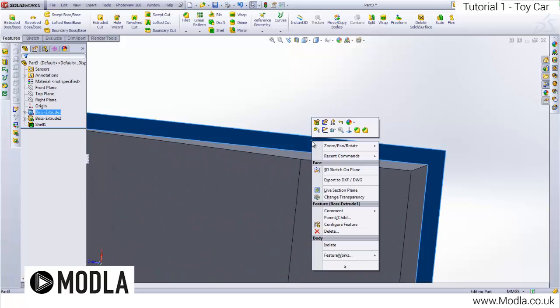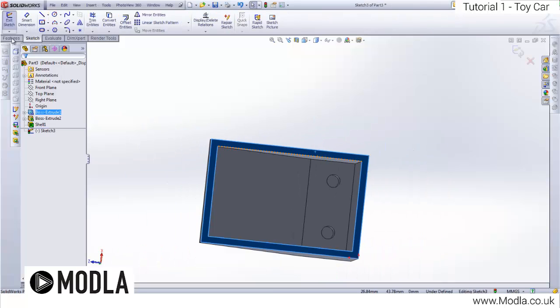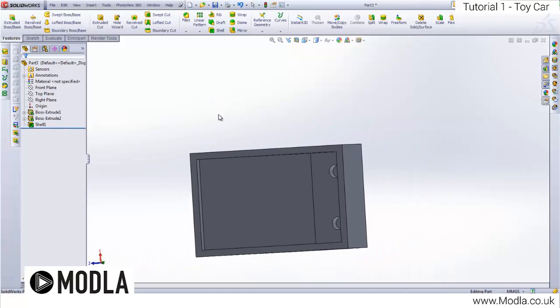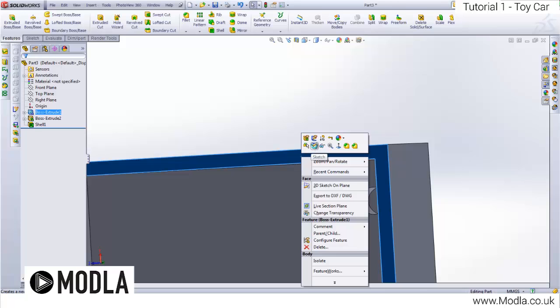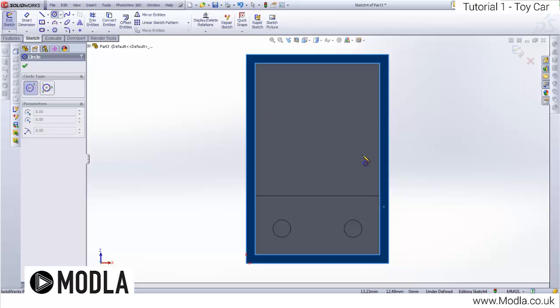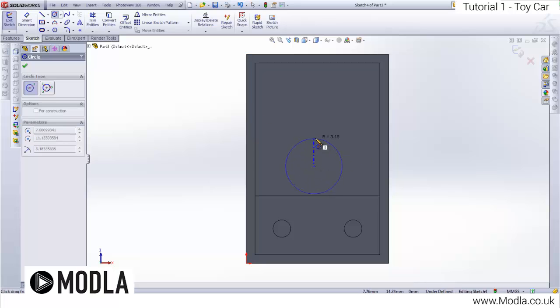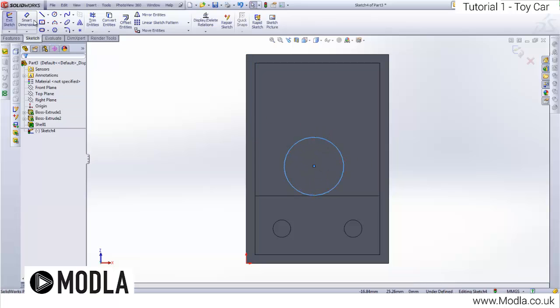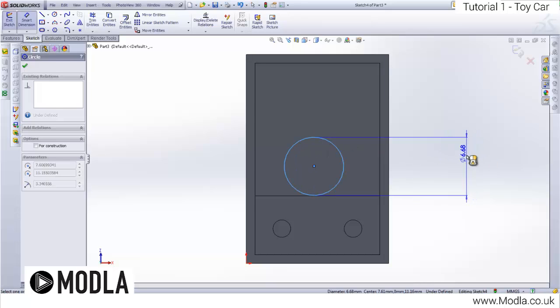We need a nice flat edge to use, so we're going to go sketch. I'm going to use the sketch in here, so I'm going to click on here, go sketch. I'm going to click on my spacebar, normal to. Now I'm going to create a circle, somewhere like so. Now once again, remember before, that was 5.4.